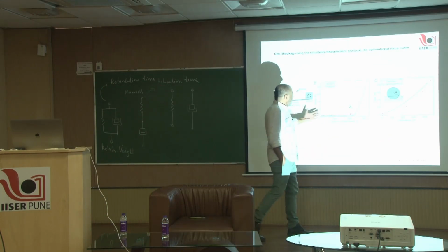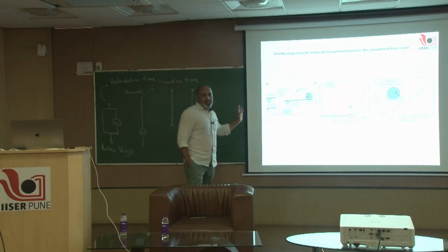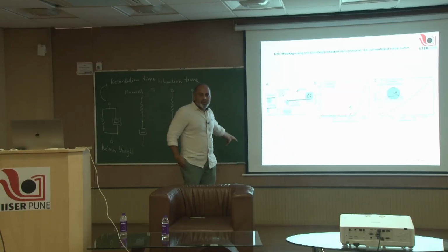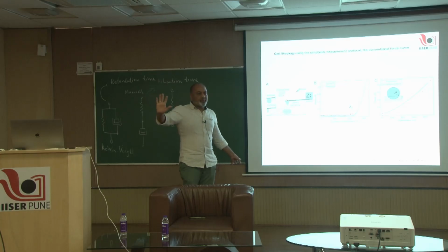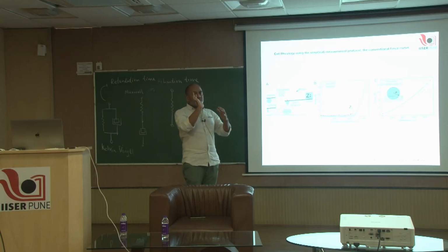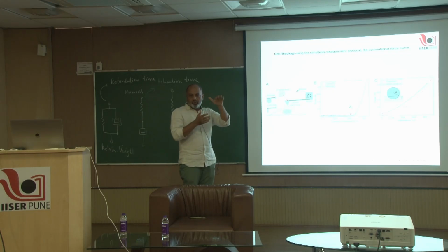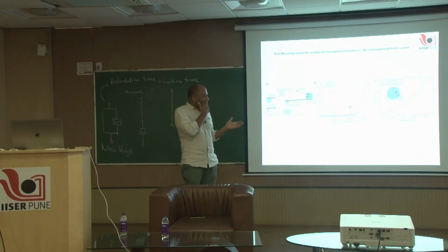What is being done is that all the protocols we looked at, except for the first one, are really nice, because we apply some constant voltage to the piezo and now see how the deflection of the cantilever is relaxing, and you follow that, it will be like a power law or whatever. Or apply a constant stress and see how the creep develops in the material, and apply again the same power law.